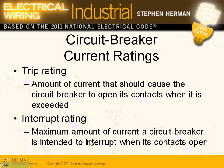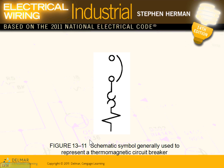Any questions, guys, about this? Your thermomagnetic circuit breakers. Before I leave this one, guys, this is the old technology. The new technology is called electronic circuit breakers. They have sensors inside the circuit breaker. That's exactly what they do. A sensor senses the current. I'm just showing one phase; this is a one-line diagram.